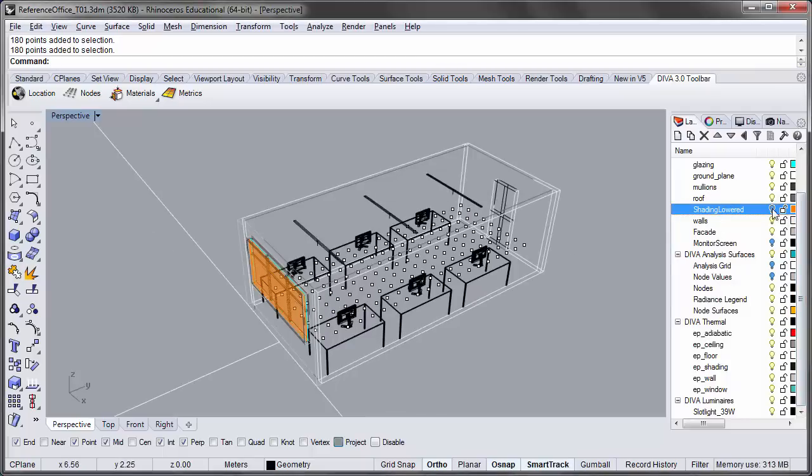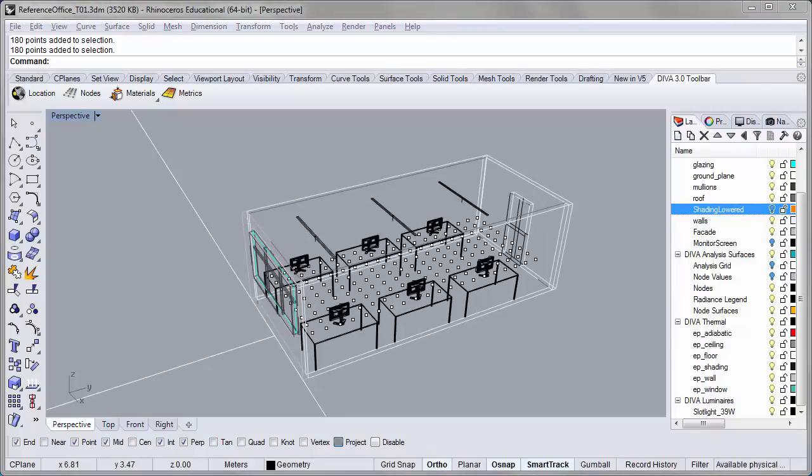The calculation that I ran in the previous tutorial for the dynamic shading control groups already calculated the geometry of the shading, which came into play for determining the daylight coefficients for the daylight autonomy, and so I'll still be able to generate those shading control group schedules when I run daylight autonomy, and I'll be able to just reuse those daylight coefficients to quickly evaluate the different lighting control schedules and predicted electric lighting energy use that will be based on this annual metric.